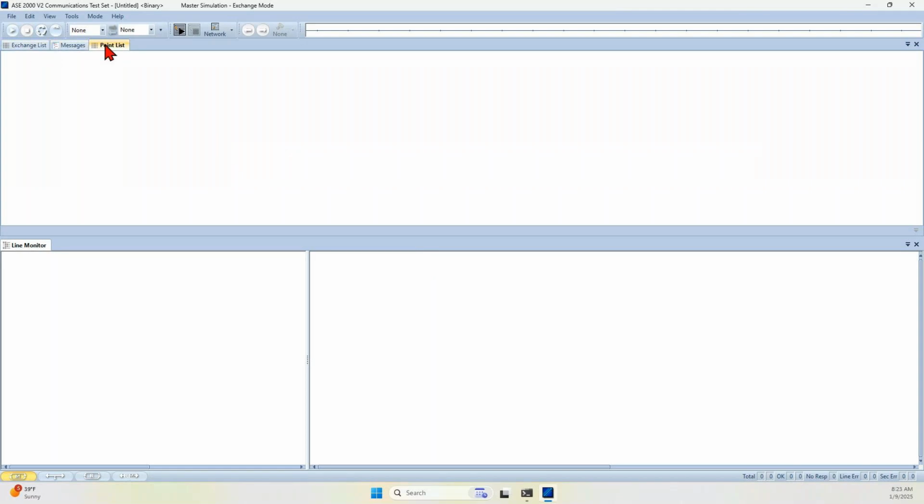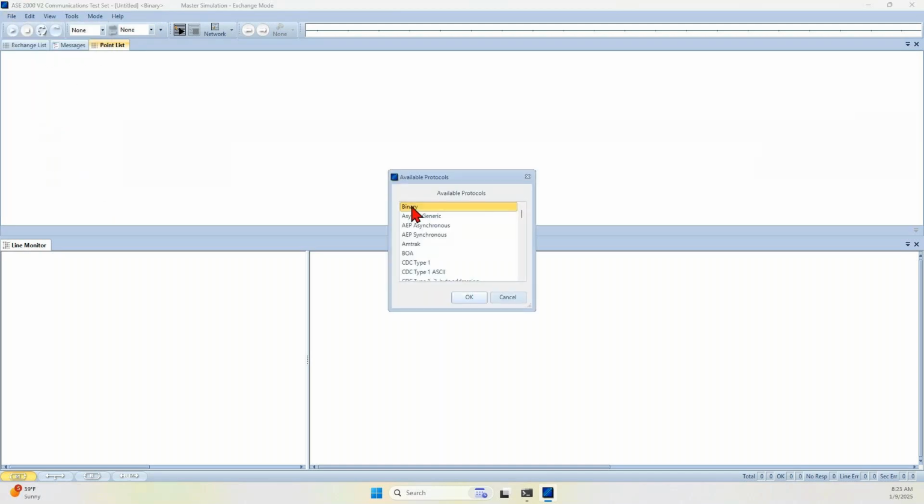the software, you will see mostly the binary protocol. And if you browse to the select protocol option, you can select SunSpec Modbus or Modbus serial. So serial or TCP options are available. If you have a serial SunSpec Modbus device, you will be able to use the serial. And if you have a SunSpec Modbus TCP device, then you can use this TCP option. To make things easier, during the demonstration, I will use the TCP.